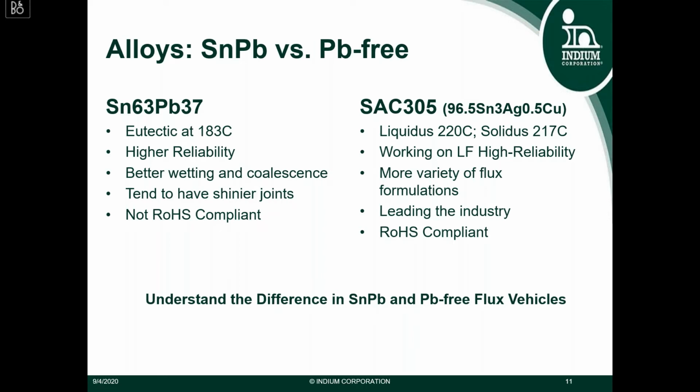In a lead-free flux vehicle, they're designed for lead-free alloys, which means that the excessive lead oxide that forms on lead cannot always be compatible with the chemistry designed for lead-free. In many cases, however, there are flux vehicles that work for both leaded and lead-free solders. You'll have to ask your solder supplier if that is an option.